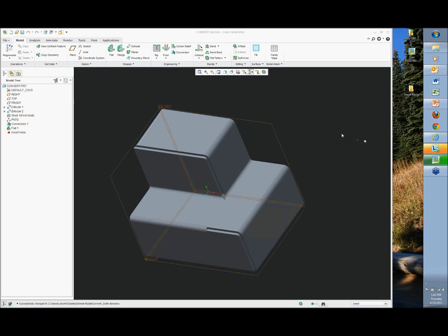Most people are using the default bend deductions, so 79% said yes to the default bend deductions, 21% no. So that just tells me the 21% no are probably sending this right out to manufacturing and are going to use it. The 79% that said yes might be using outside sources for manufacturing. And it's fine, if you're sending them out that way, that's great. If you want it to be a little bit more accurate, then you got to start thinking about using the bend deduction tables, right? So we have a couple using bend deduction tables here.